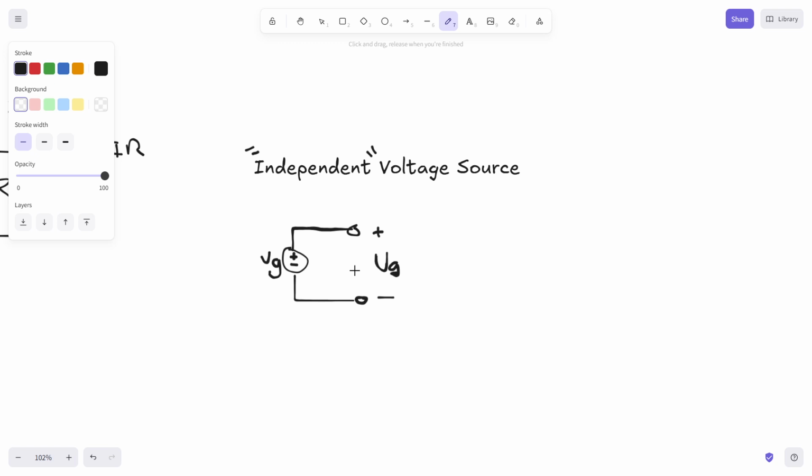This would be like if you unhooked the car battery from your vehicle and you measured the voltage across the battery. Technically, it is producing a small current that will pass through your multimeter, but still, in the grand scheme of things, that is a minute current that we don't really care about, and we can see that there is a voltage across those terminals at all times. It's not just when it's hooked up to your car. And for our purposes, that looks like an independent voltage source, because it's going to be 12 volts practically all the time. There's some parasitics that come into play.